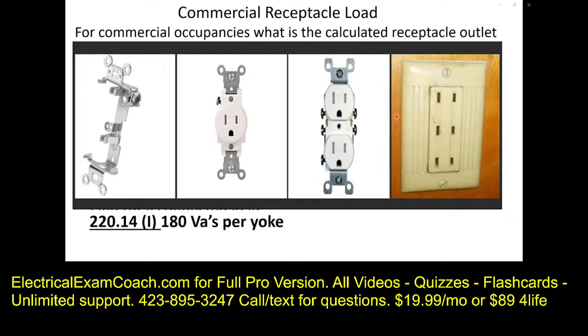So if I have a single gang box, it's 180 VAs. If I have a two gang box and they're both containing receptacles on each side, it would count as 180 VAs per gang, and so on and so forth as you went to 3 and 4 gangs. Anytime you're dealing with a device strap, whether it has 1, 2, or 3 receptacles on it, it's 180 VAs per yoke. Now, let's check for demand factors.